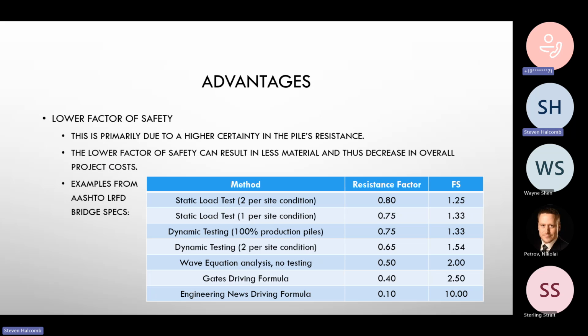And so the benefit of the PDA is that you can hit it once or twice, and it'll get at the strongest point of the pile, at that low in the pile, and you'll get that measurement. And so you'll be able to detect in one blow what the capacity is, versus having to count how many blows per foot, how much did it move in that one blow, like a quarter of an inch or so. It gets really hard to do it without the PDA.